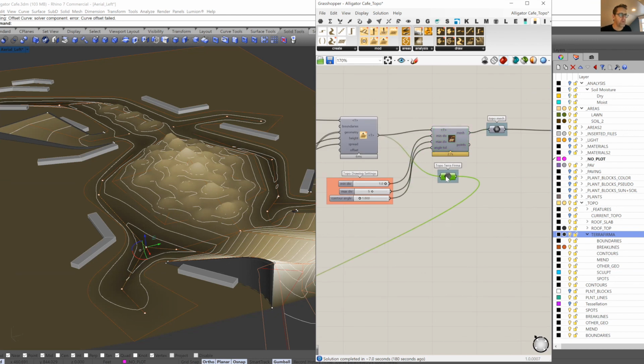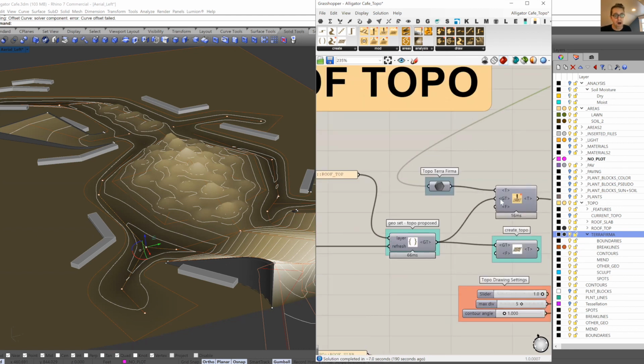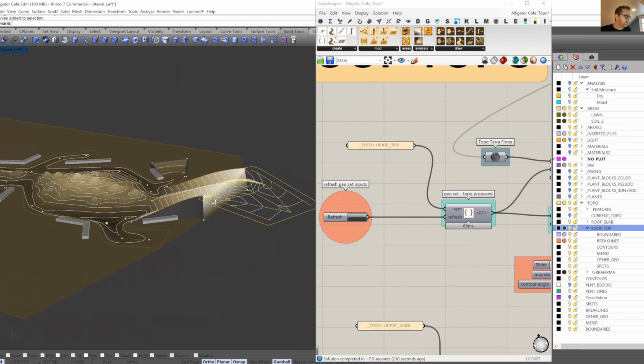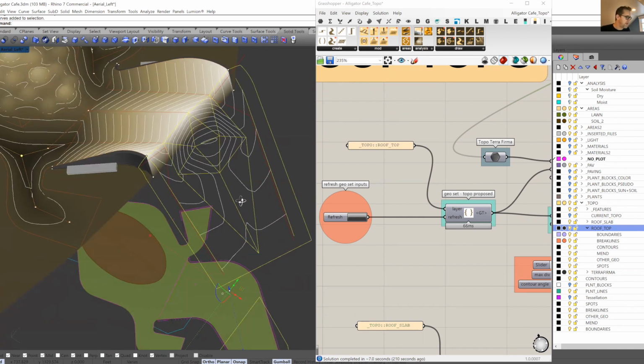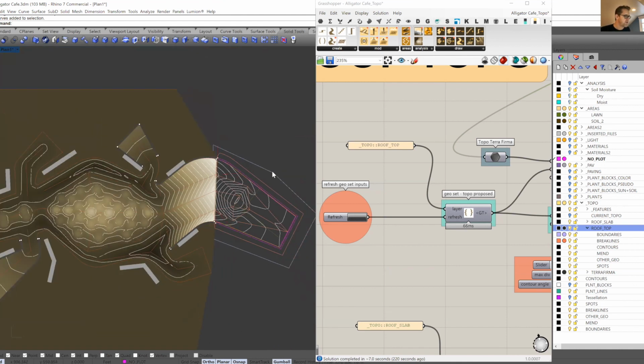That topo, before we draw it, we're actually going to take it and it's going to come down here, and we're going to make another mod to it, which is a patch mod. The neat thing about the patch is it still requires an input of a geoset, which we get from a series of geometries. So if I select all the sublayer objects of that, we have some break lines that define our roof. And then we also have a boundary down here in purple that defines, let me just go to plan, that defines that area.